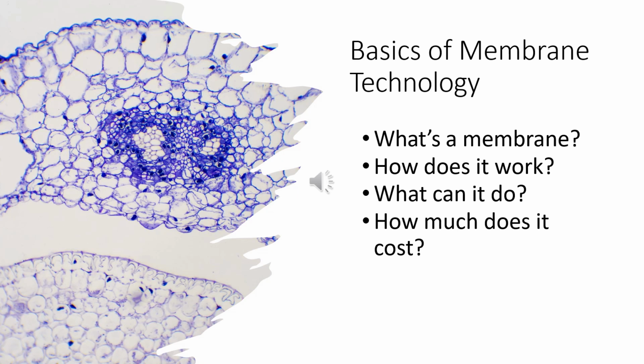And how much does it cost? Among the disadvantages of membranes are the high cost of the membranes and a slow filtration speed. According to the pore size or molecular weight, filtration membranes can be classified into different types, such as microfiltration, ultrafiltration, nanofiltration, and reverse osmosis membranes.